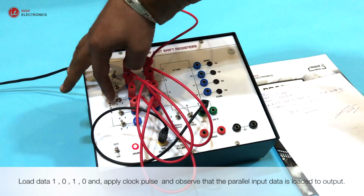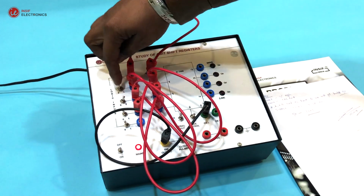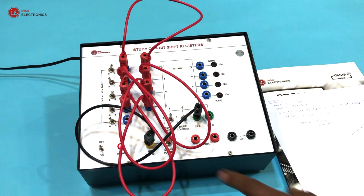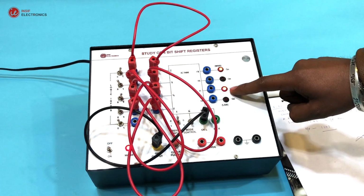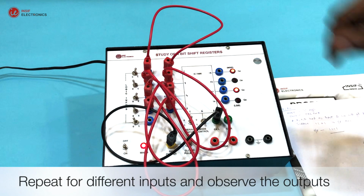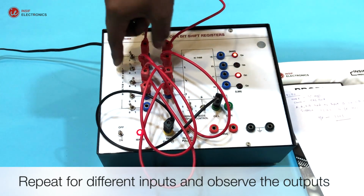Load data 1, 0, 1, 0 and apply clock pulse, and observe that the parallel input data is loaded to output. Repeat for different inputs, and observe the outputs.